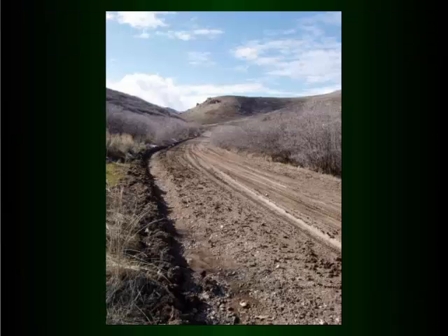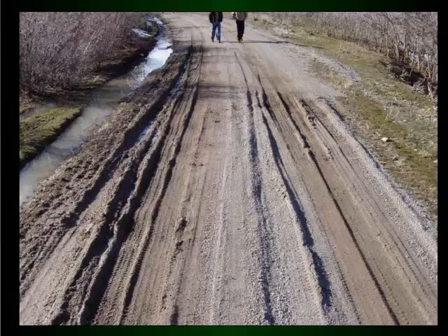You're seeing some rutting action in the road here. This is a spot where you see standing water in the ditch. This actually is a situation where there's a structure down below, so if you took a pipe across, you may end up putting your structure at risk. But you may want to consider cutting the ditch a little bit deeper in this area to get this to flow out. So this standing water means this subgrade is saturated, and you can see quite a difference from where there's no standing water in the running surface, versus where there's standing water in the running surface.